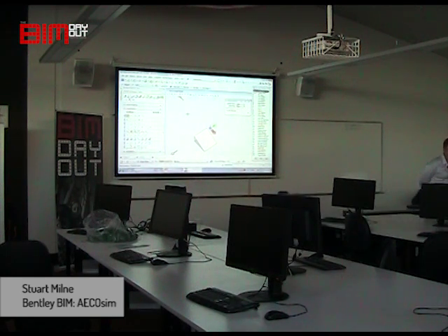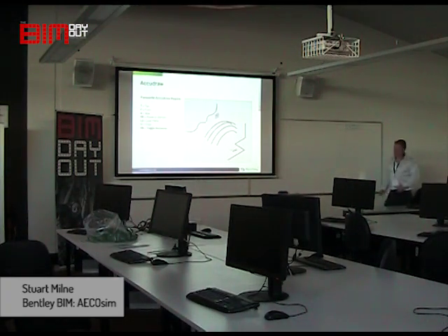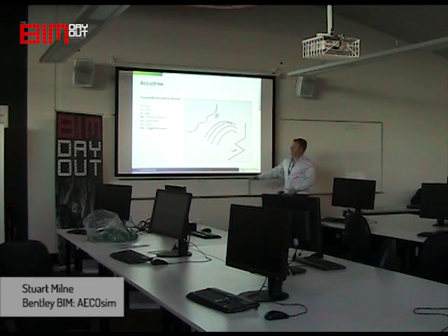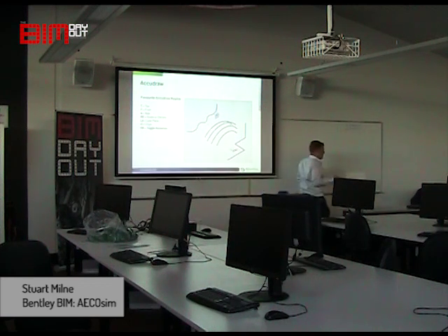We're using that geometry now. Okay, so what we can do, I mentioned earlier on, one of the key ones here I wanted to cover. We looked at T, F, and S. Now there's RE, and what RE does is it allows us to rotate the compass to the angle of an existing object.